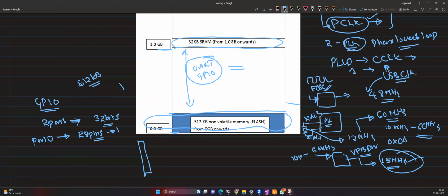Those 28 pins are for digital IO, that is ones or zeros. P0.31 is used only for analog signal. Yesterday we discussed what an analog signal is, like a speech signal, a continuous signal. Pins 24, 26 and 27 are reserved and not available for use. In the same way, port 1 is also 32 bits, of which only 16 to 31 are available for use.